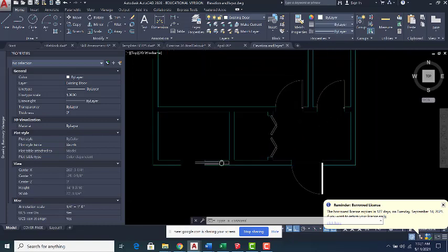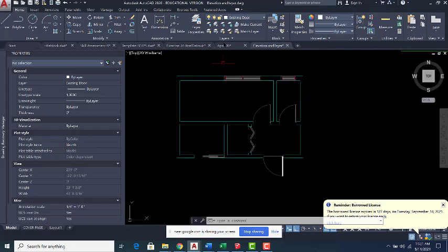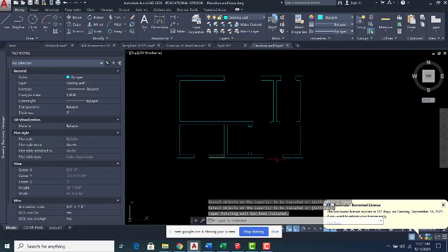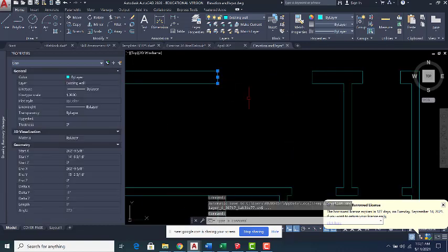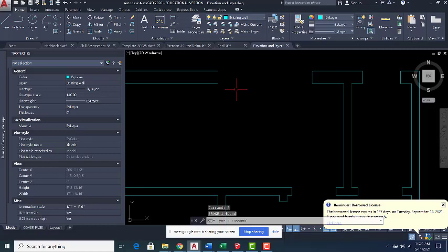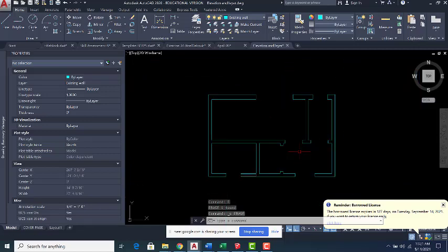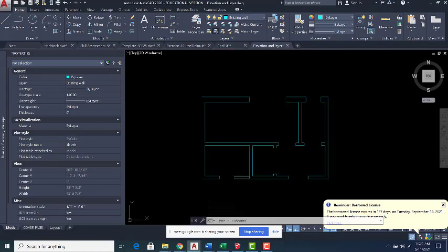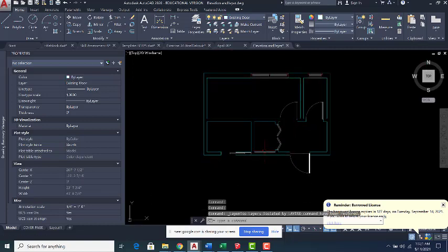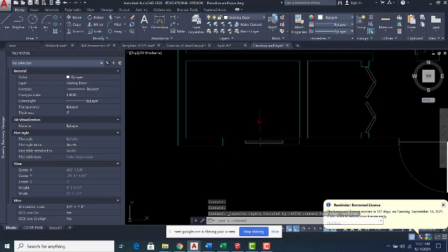My walls, see again, I show you guys the whole wall. I go to isolate, select this one. See, you shouldn't have any open area. Okay, see, if you have this part like that, it's wrong. My wall should be closed all around my plan, and then when I'm done, I unisolate. So the only thing that was new was this door.